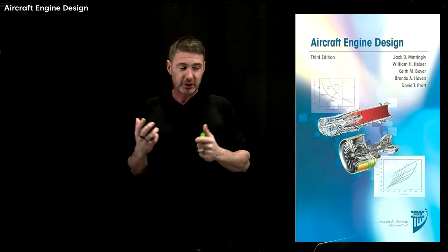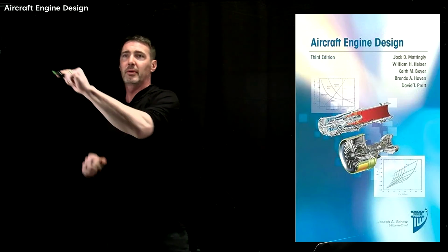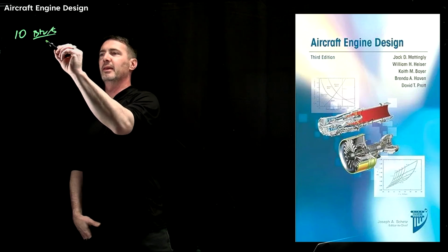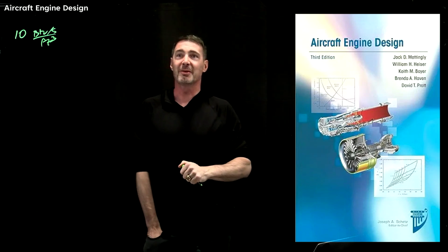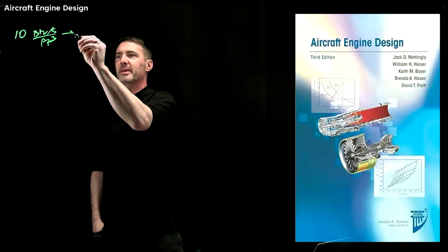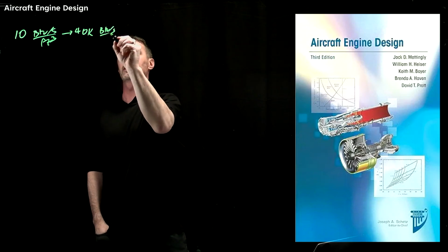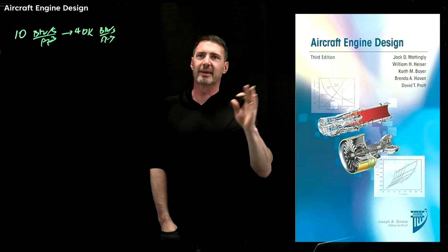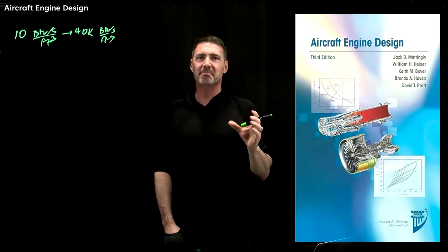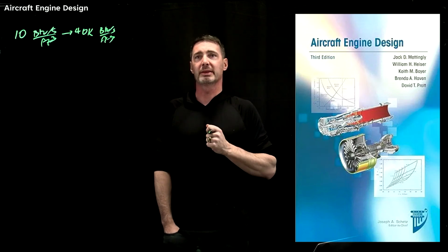And when you think about combustion, to help highlight this, if you look at a furnace, the number is somewhere around 10, all using English units here, BTUs per second in a cubic foot. But a gas turbine gets quite higher, and a rocket engine is even way more than this, right? A gas turbine is closer to 40,000 BTU per second per cubic foot. And like I said, a rocket engine is way more than that. So these are pretty power dense systems. That's why they're great for aircraft. That's why even on the power generation side, they're pretty useful.